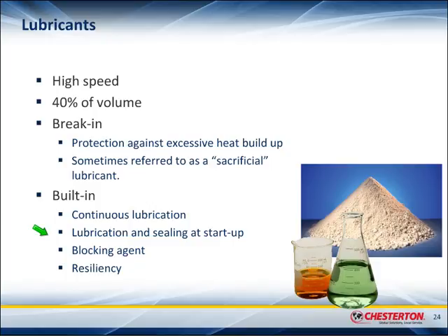So when you compress packing further, this lubricant releases itself and becomes available to provide low friction. And these built-in lubricants act as a blocking agent. What the built-in lubricants do as well is they make sure that the individual fibers slide better over each other, so it actually improves the resiliency of the packing itself.